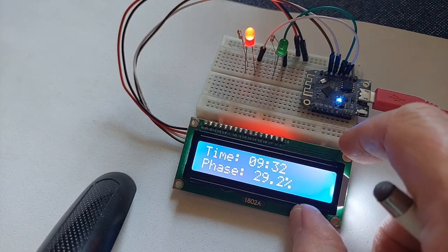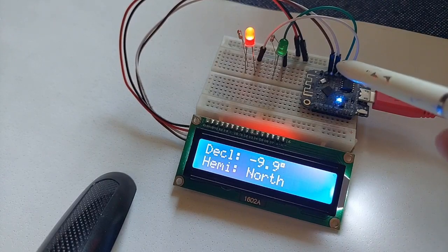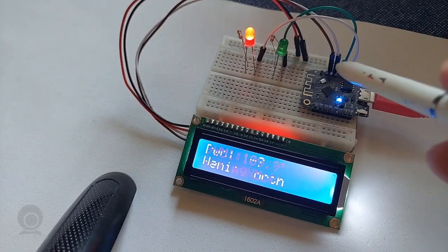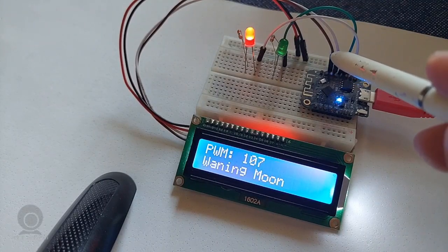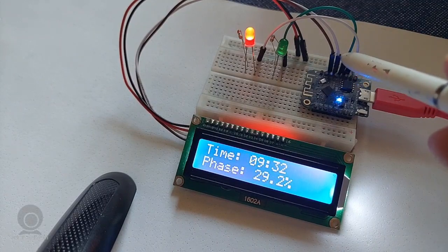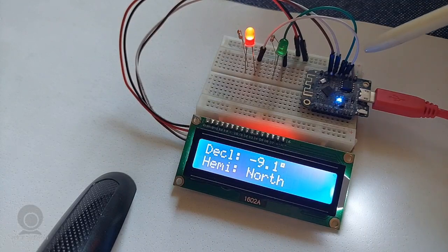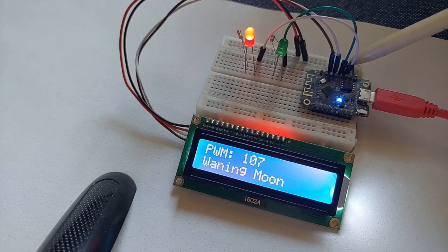This is I2C, so it's using only two wires, SCL and SDA. SCL is on D1 and SDA is on D2, pin 2 or D2. Okay, here's a rail. It's a 5-volt rail and the ground, so you have a ground and a rail.